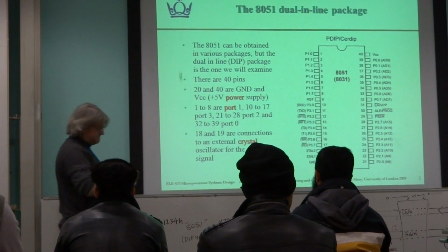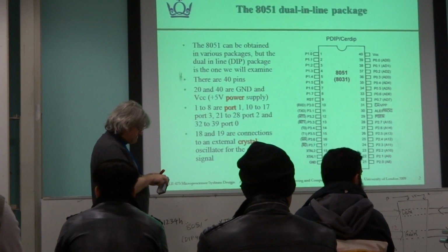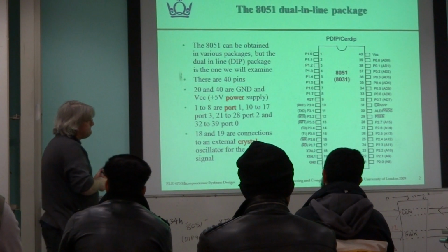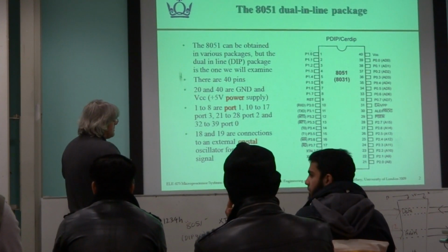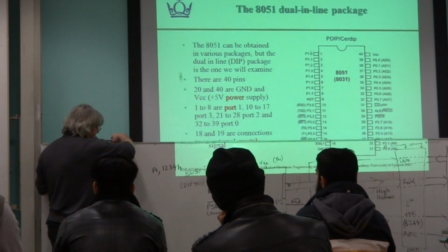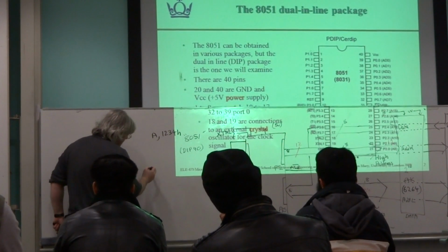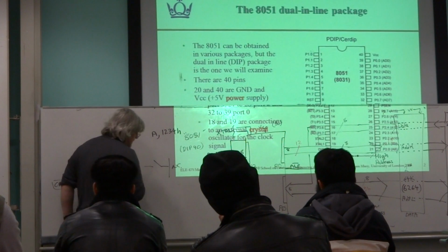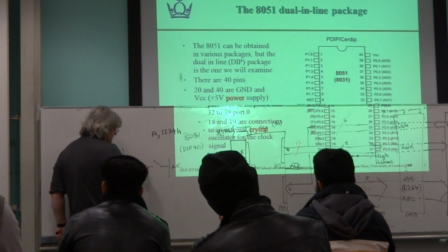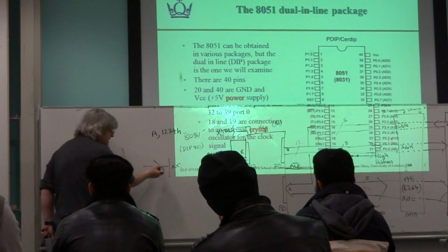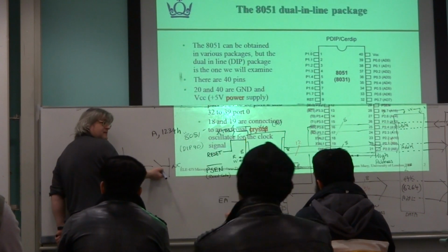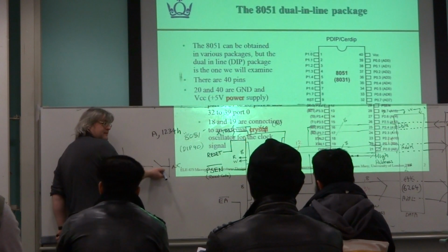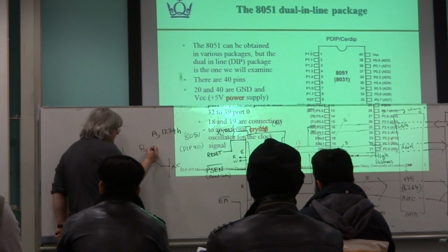Can you explain a bit more about a pull-up resistor? Because I have seen that normally push buttons and switches are connected with a pull-up resistor. It just means, if you had a switch into a device, such as a microcontroller, and you just leave it like this, well, the question is, when it's open like this, what's it going to read? I mean, it's floating, as you said, the technical term is floating.